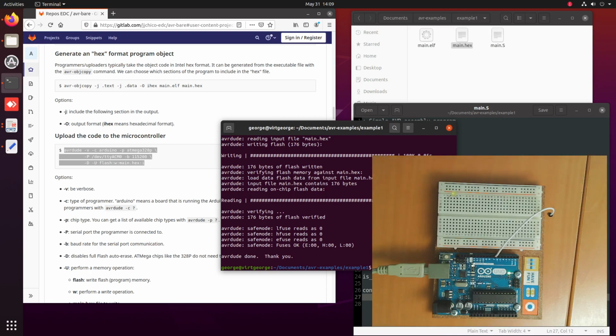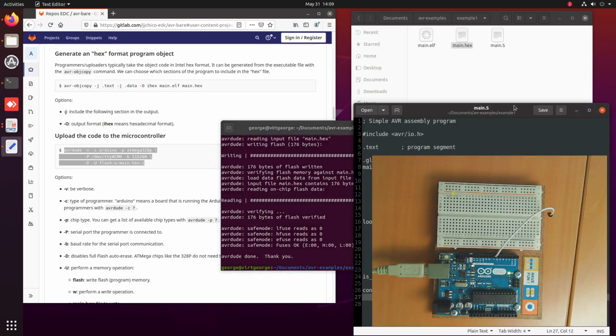Okay, so we will add that to our code. The pull-up resistor is configured by the PORTD register: when DDRD makes the pin work as an input, the PORTD register determines if we activate the pull-up resistors or not.